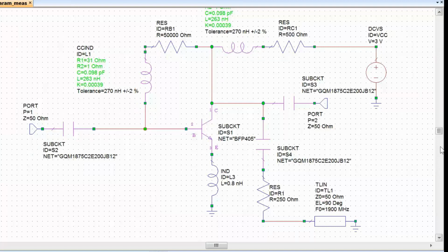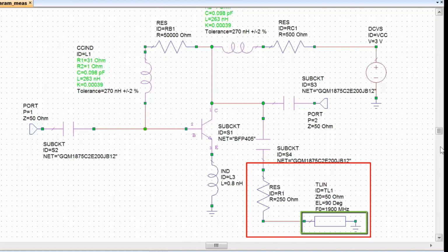We also looked at the importance of stabilizing the device. Since we tried to match the input, we saw how by using specific terminations at the input, which would improve the reflection coefficient, we then ended up having an unstable output port. So we looked at different ways to stabilize the transistor, and then finally we went for a configuration which entailed having some inductive emitter degeneration, and then also a bit of resistance in shunt with the output, which will not affect us at the frequency of operation through a quarter wave transformer, but which would help with stability at lower frequencies.